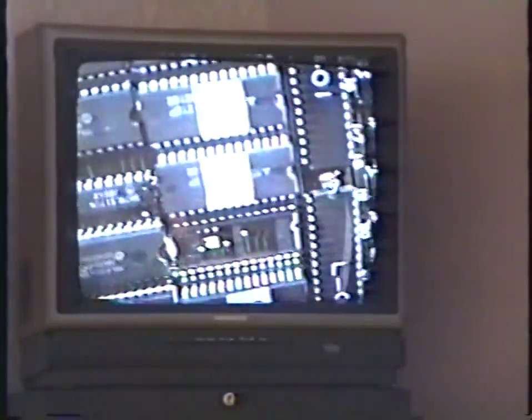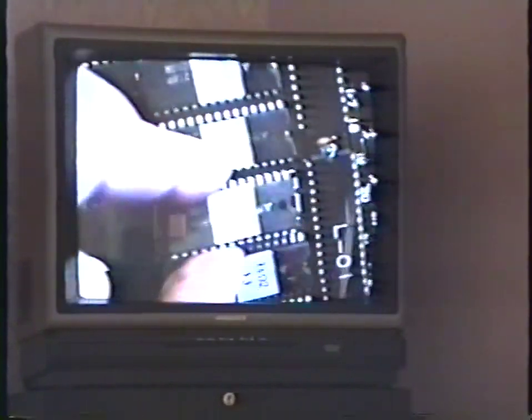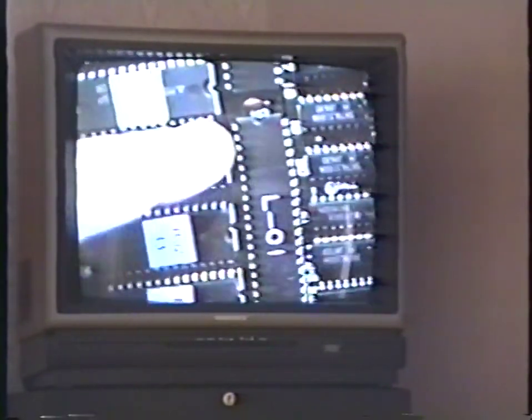When you go to put this thing back in, be observant. They fit both ways. They fit this way and they fit this way. They only work one way. The other direction they blow up. Well, they don't really blow up, but they fail. You'll notice that all the notches are pointing the same direction. See, notch, notch, notch. Those notches there. All right? All going the same direction.